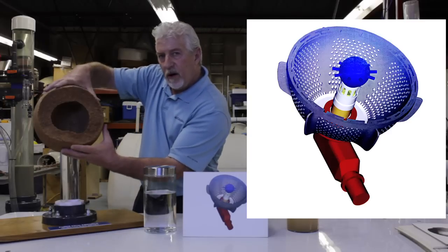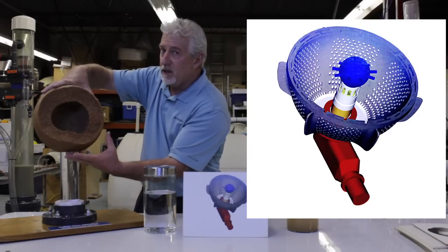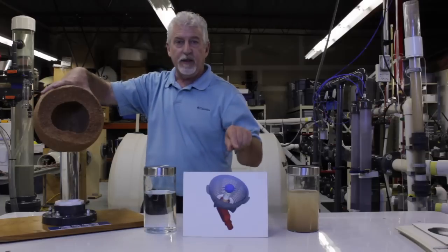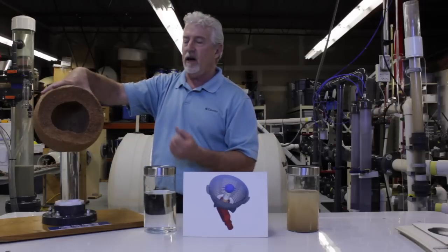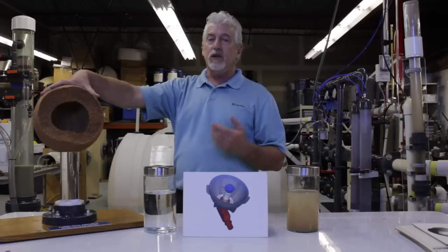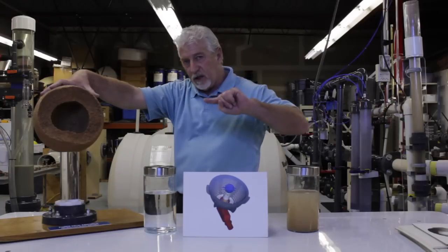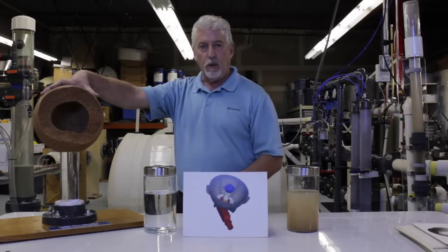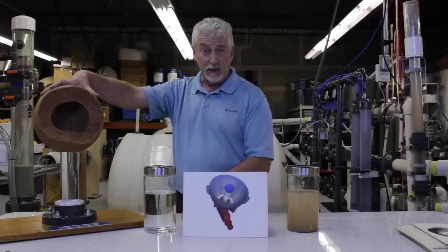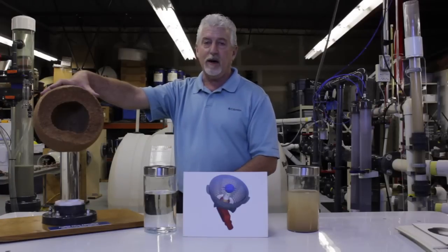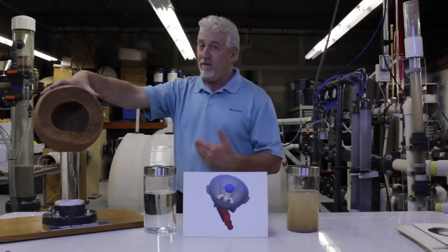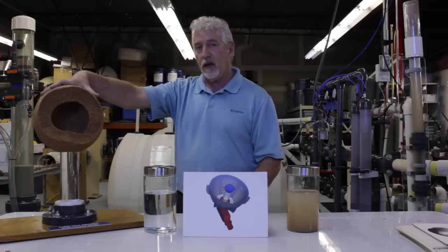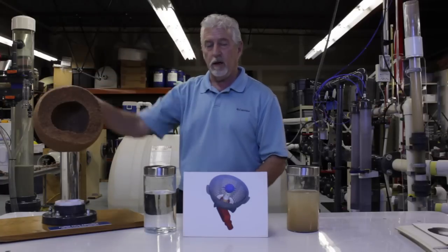Now remember, we've uncompacted the media, it's fluidized, but it's still captivated. We've got these Gatling guns of spa jets hitting it at 16 feet per second, 250 times the velocity of the slow conventional sand filter. Our backwash cycle went from 3 to 5 to 10 to 20 minutes of the conventional down to 20 to 30 seconds. Fast, saves over 90% of the wash water required.